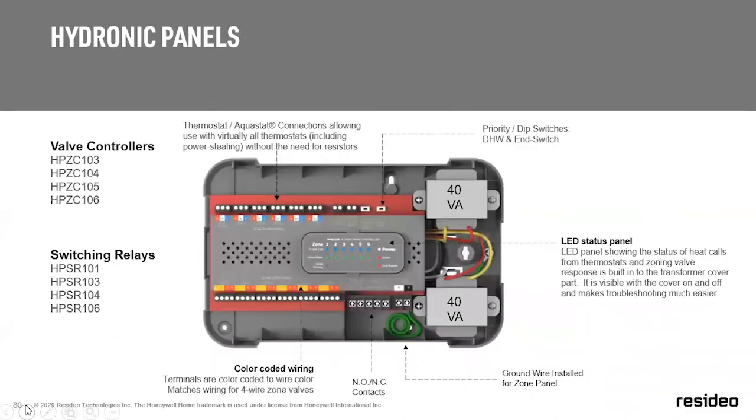And then we also introduced last year new hydronic panels, both valve and switching relays. The nice thing about these panels on the valve controllers is they come with 80 VA, and the transformers are thermally fused. So if you've got a new technician who bucks a transformer, it's going to heat up, cool down, and reset itself. The board is also fused, and there are spare fuses on the board itself.